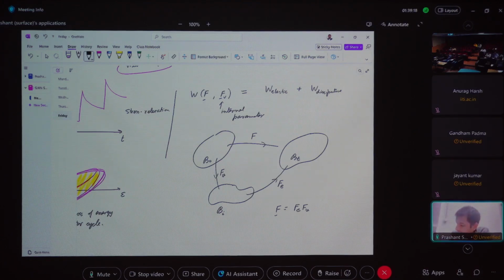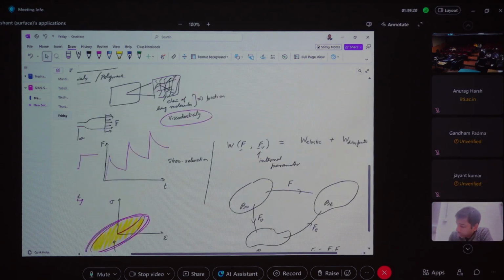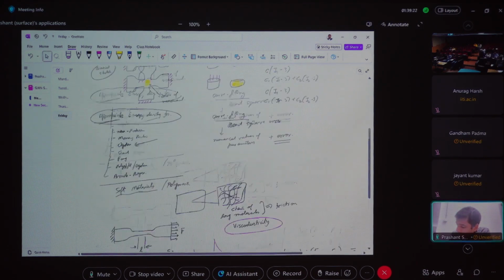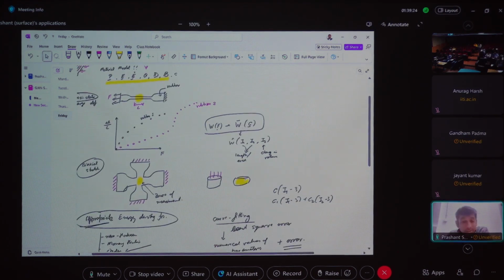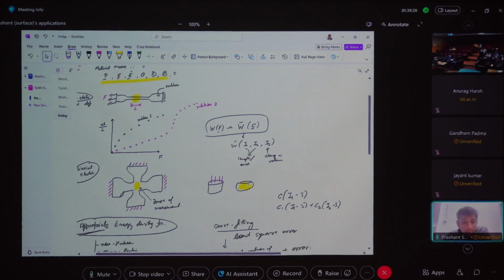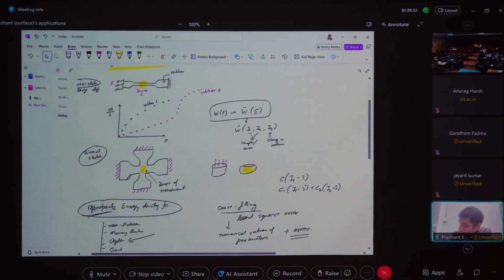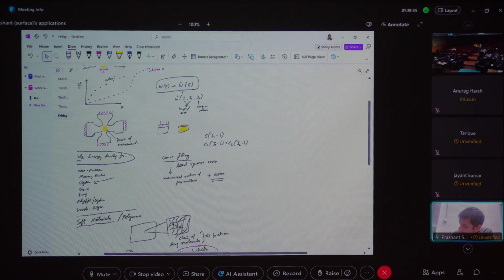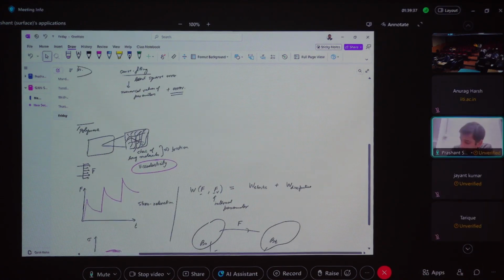So what we were discussing earlier, you do experiments like these three experiments, but now you do them with quasi-static plus also rate dependence, because at the end of the day, your job is to find out what is this W. How do I find out the formula for this W so that I can actually get a material model for my material?